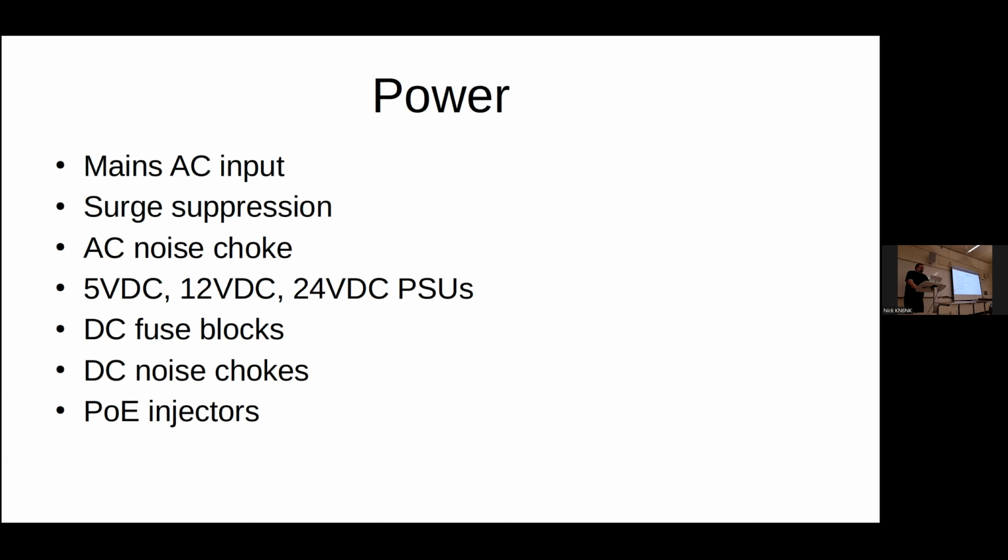I've got some DC noise chokes that I also added for anything that is actually doing RF stuff, just to keep any of the switching power supply ripple out. And I've got some PoE injectors for the network gear.